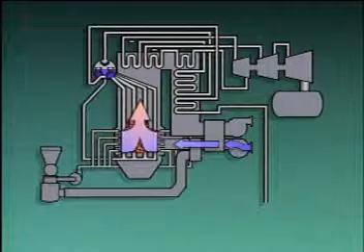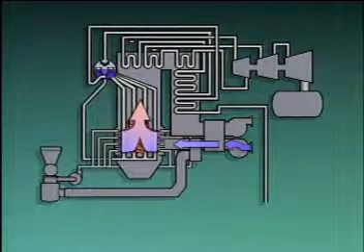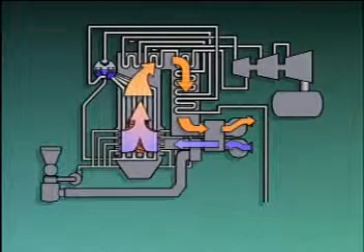As fuel burns in a boiler furnace, air is brought into the boiler to support combustion. During the combustion process, hot gases called flue gases or combustion gases are produced. The hot combustion gases flow out of the boiler. The combustion gases that leave the boiler furnace contain a great deal of heat. In most boilers, as much of this heat as possible is transferred to steam, boiler feed water, and incoming air. This way, less fuel is needed in the boiler furnace and the efficiency of the boiler is increased.